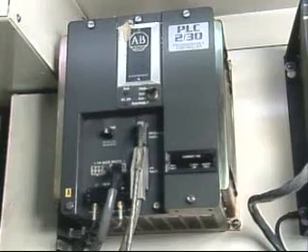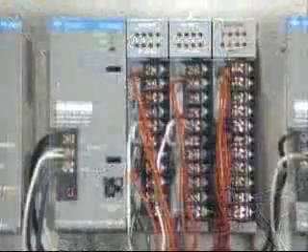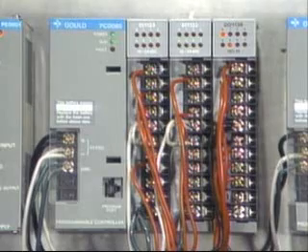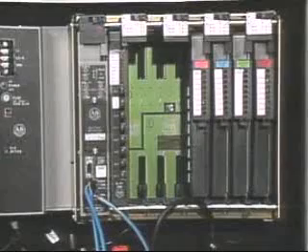A programmable controller is a computer-based process control device. Programmable controllers are commonly used to establish protective circuits, such as safety interlocks, and to control operations in sequential process systems. When programmable controllers are used in these and other applications, the control logic that determines the actions taken and their sequence is easily programmed into the controller. The programming consists of a set of instructions called a control logic program.